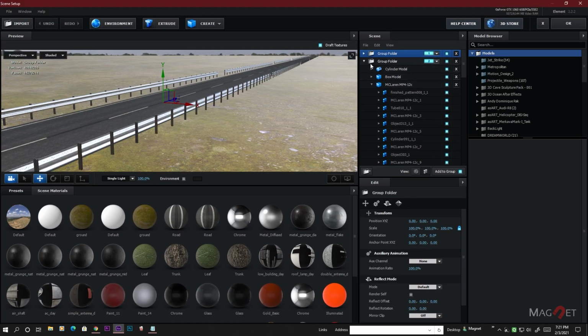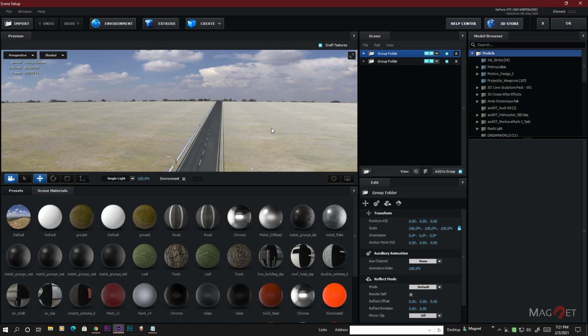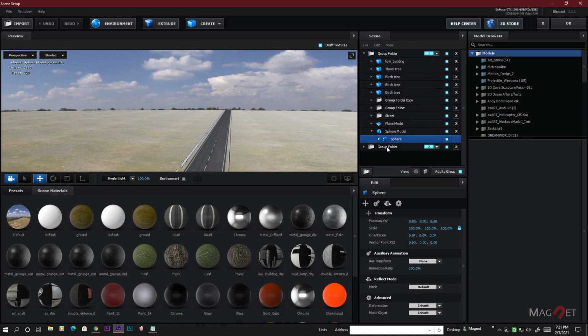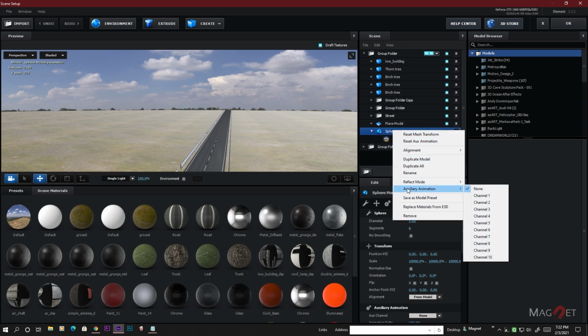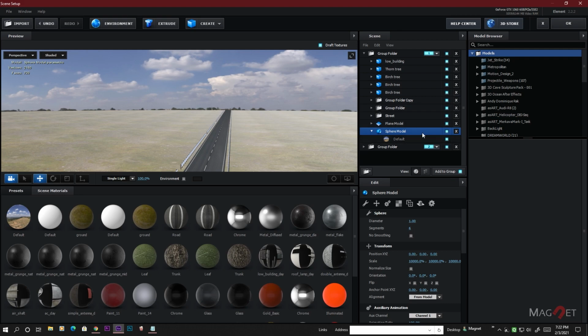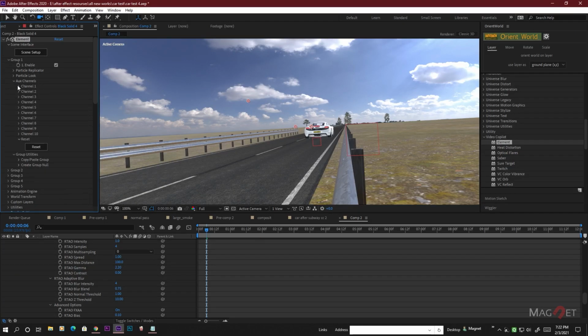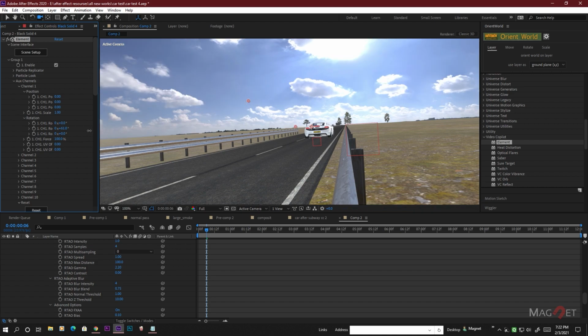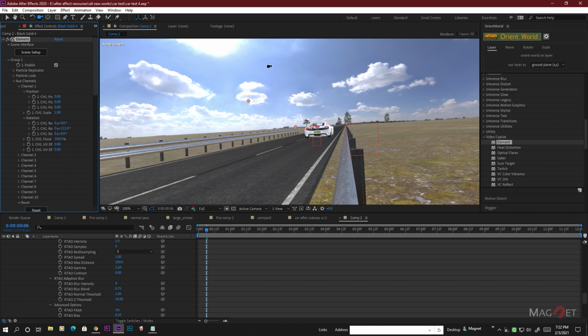and we go to group number 1 here, and first we select our environment sphere and place it in a different auxiliary animation channel, that is channel number 1, and this auxiliary channel is inside group number 1. So now hit OK and go to group number 1, go to auxiliary channel number 1, go to the rotation, and now you can rotate the entire environment like this. Okay, so now we have our sun on the left side.